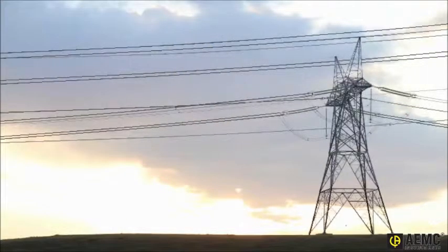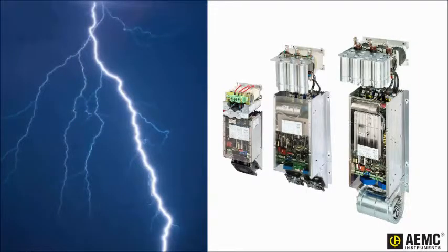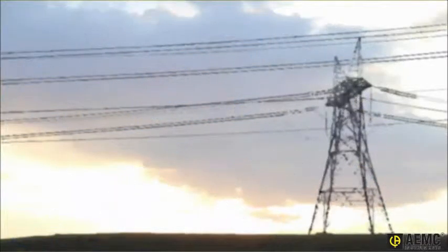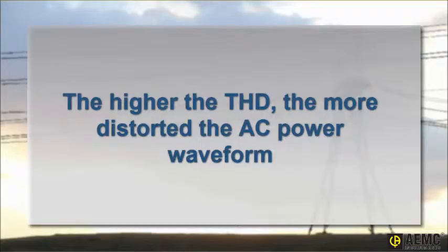In an electrical power line, a number of factors can create harmonic distortion. These include currents introduced into the line by users of nonlinear loads, environmental causes such as lightning, electromagnetic interference, and others. As a result, the AC electricity delivered to a facility can include a significant percentage of THD, in addition to the fundamental sinusoidal electricity produced by the power generation plant. The higher the THD, the more distorted the electricity's waveform.